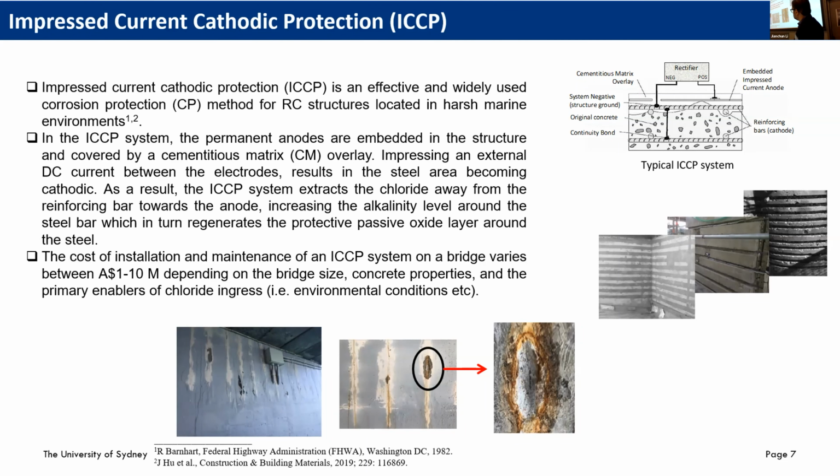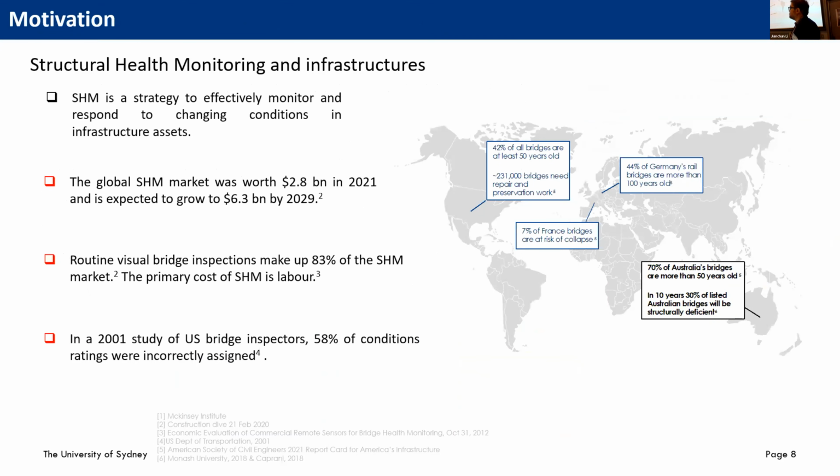So obviously, if we can improve this performance using structural health monitoring techniques to give us some understanding before initiation of corrosion, we can mitigate that initiation and prevent the corrosion from progressing. Then we can save a lot of money, obviously, and also increase the service life and the sustainability of the structure.